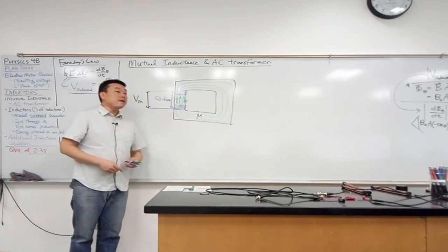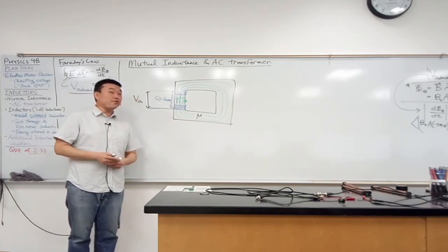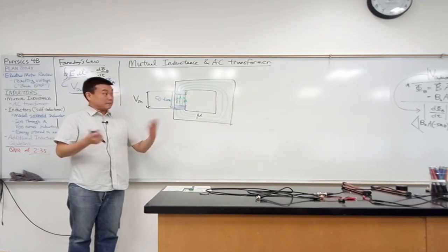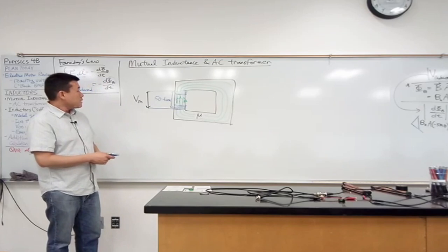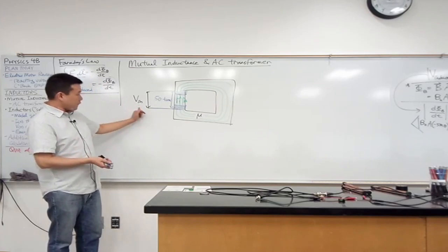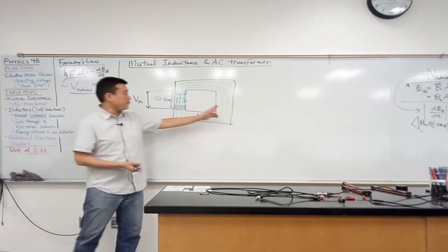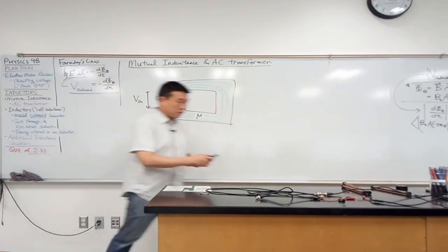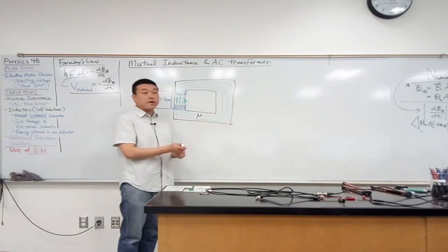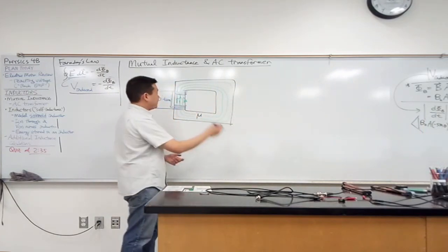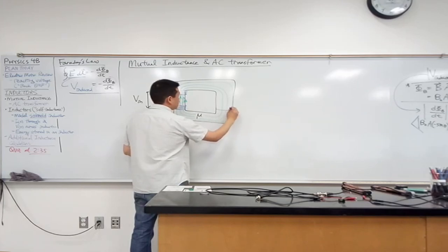This variac, you plug into 110 volts, but it claims it can give you 140 volts. So you could sometimes get higher volts. We'll see that in a demonstration in a bit. So to get a different voltage out, what you do is you wrap a different coil of wire over here. So this is the second set of coil windings that's in that variac. So you wrap a different set of wires here.